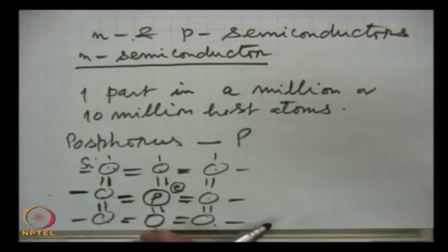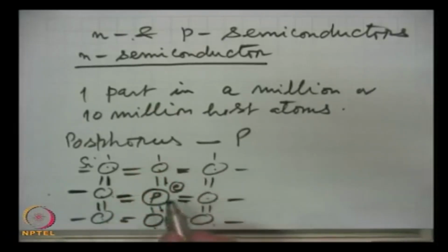How loosely bound? We can calculate it as we did for the binding energy of the electron in hydrogen. There the electron moves in vacuum, here it will move in the material, so the permittivity of the material will enter. The real part of the dielectric constant for silicon is around 11.5, so the force on this electron from its parent atom phosphorus is reduced further by this amount, and it works out that